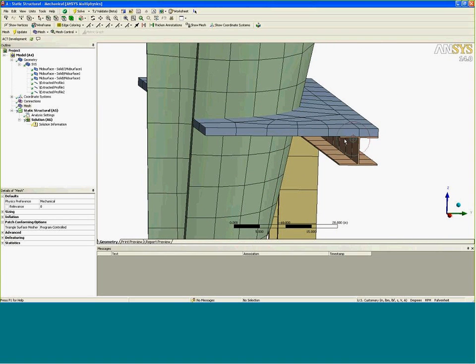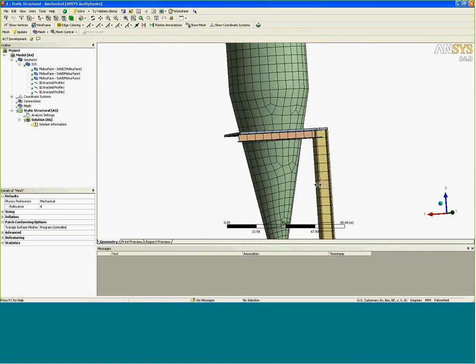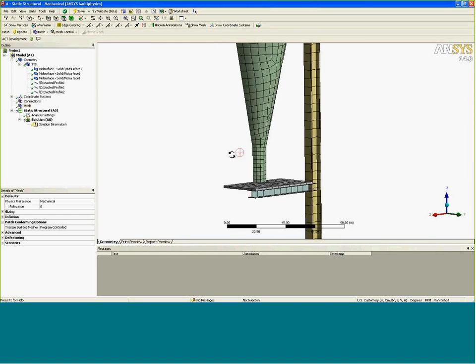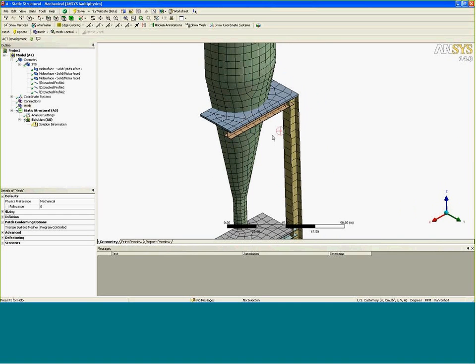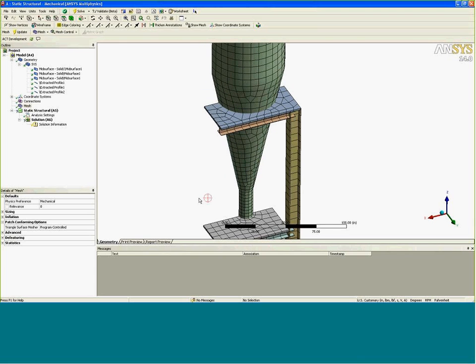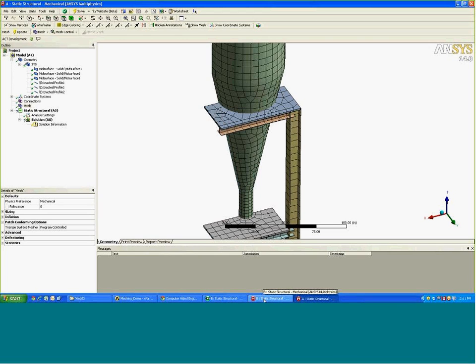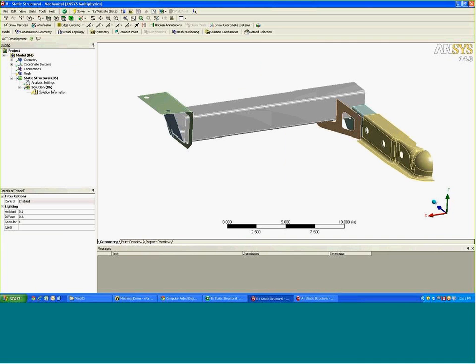We can see that these cross sections are aligned where they used to be in the geometry, but they are connected up at the mesh level. So that's nice and easy to visualize. Same thing down there; those are all connected up. So it's fairly straightforward. If you bring it in and everything's connected, you can just go ahead and mesh it as is. So let's take care of things on the CAD side. We do need to bring in these beams and surfaces from somewhere: CAD, Design Modeler, or SpaceClaim. So let's go to the next part now.